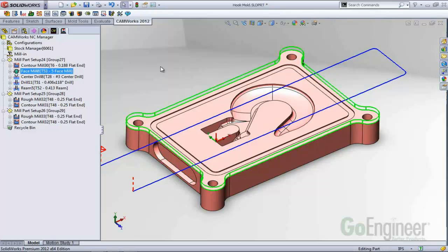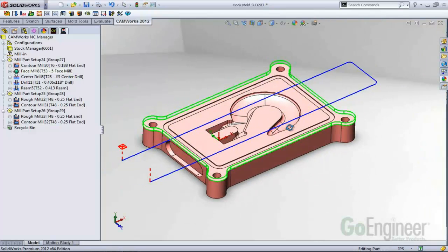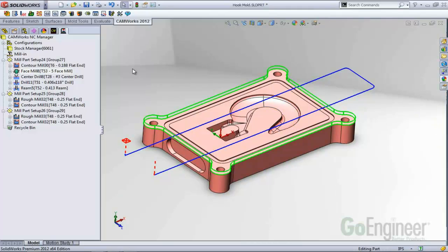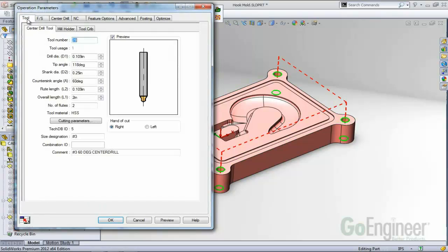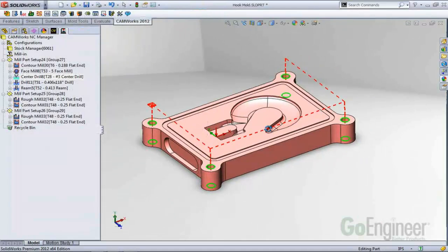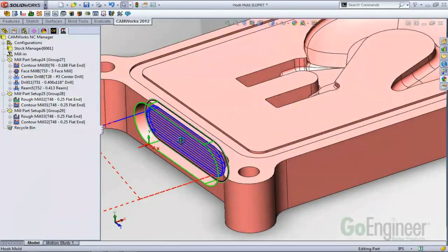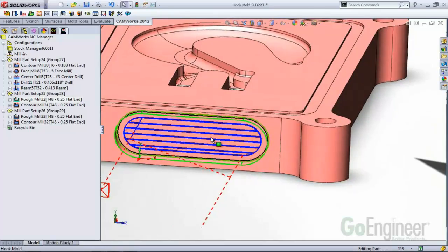And we've got some toolpath on these parts now. Again, the tools that it chose, the depth, feeds and speeds, side parameters, bottom allowance, NC planes, lead-ins, lead-outs, all of those operation parameters, the nitty-gritty details that make up each of these operations, are all pulled from the database at that point. So it's our job as a CAMWorks programmer to take what the database gives us, evaluate it visually, just to confirm that it's given what we want, and then adjust accordingly.